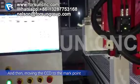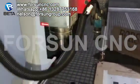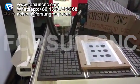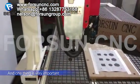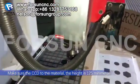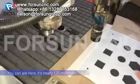And then move to the CCD. Move to the mark point. One thing that is very important is to make sure the height from the CCD to the material is 1 to 5 millimeters. Make sure it is 1 to 5 millimeters. You can see here, it's nearly 1 to 5.